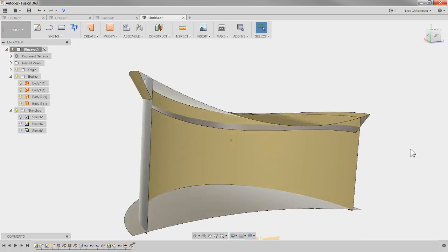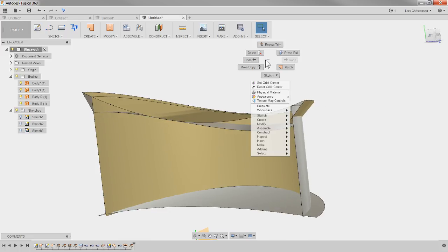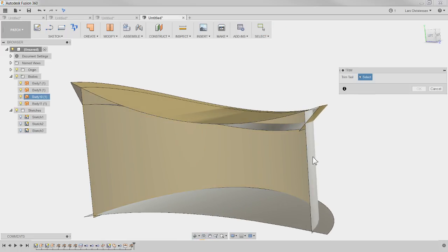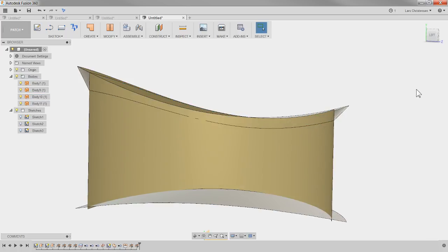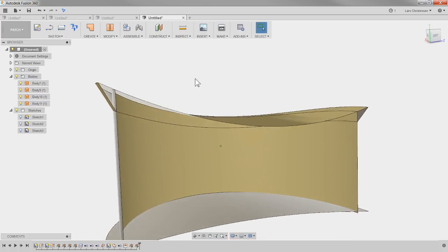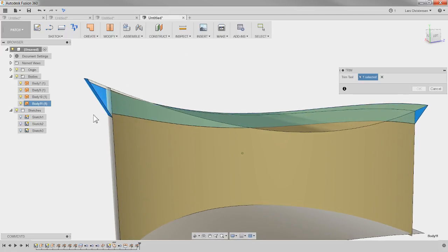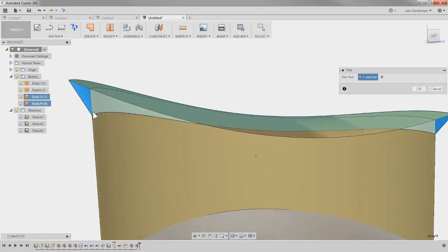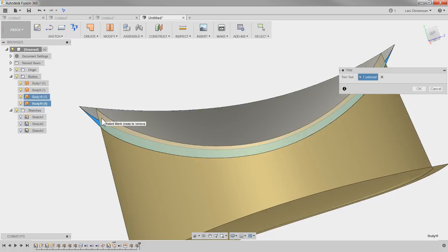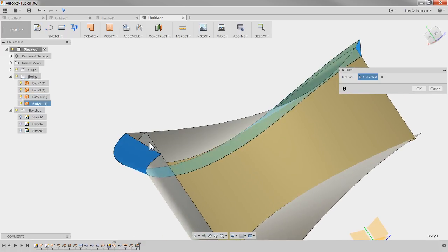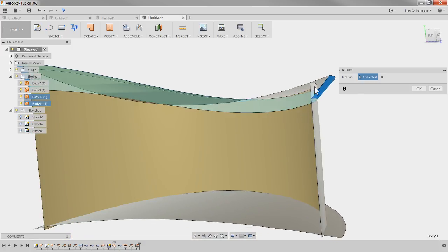And you end up with a lot of this when you're working in this environment. You will see that I'm going to have to use this as a trim tool. See if I can select this inside here, trim that to that. I'm going to right click again. I'm going to use that curve here to trim that inside right there. Sometimes it's a little hard to select. Oh, now I'm struggling. That's why we like these live streams, right?